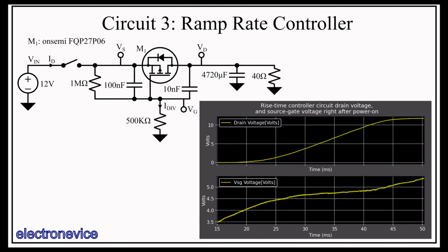Additionally, the plateau voltage is much larger, 4.7 volts VSG rather than our assumption of 3 volts. This makes the overall gate voltage closer to ground during the turn-on, which reduces the charging current, and thus also makes this output slope more gradual. We also haven't closely examined the nonlinear behavior of the parasitic capacitors of the FET, nor have we dealt with errors in the component values, especially frequency-dependent ones. Additionally, the setup is a breadboard without a ground plane, which may have hidden parasitics, adding even more errors.